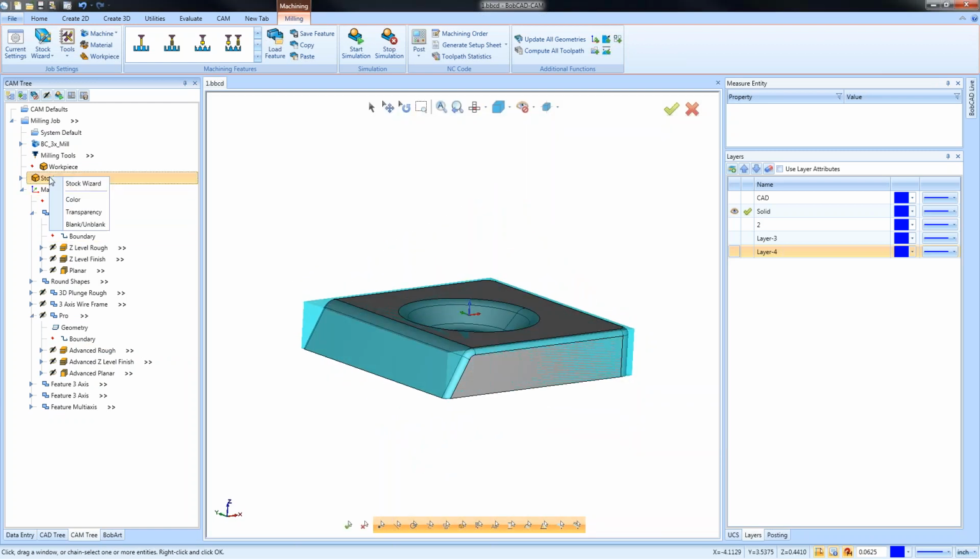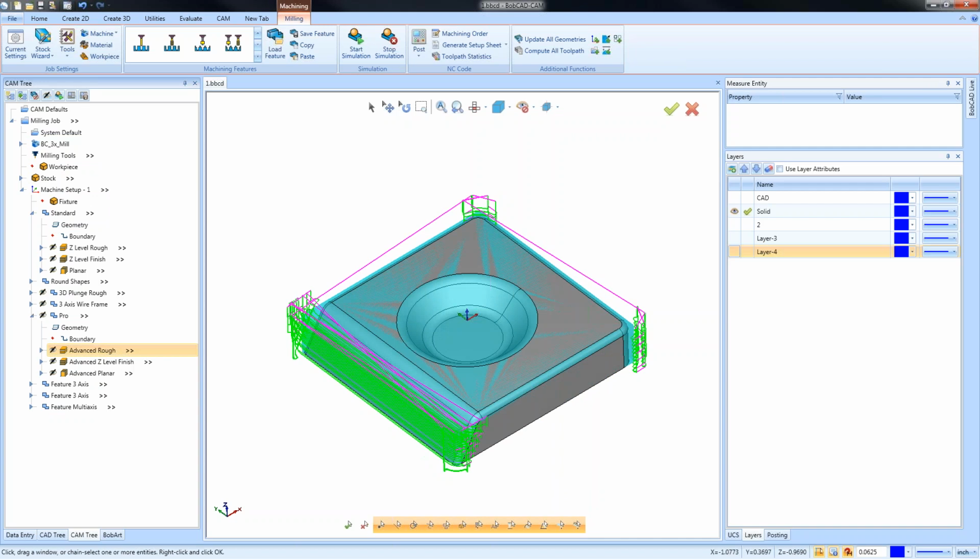So let's go ahead and I'm not going to get into controlling. That's going to be day 2, but again, the main difference that I'm focusing on right now is the way the toolpath is generated based off the stock. Zlevel Rough, the center of the tool will go to the stock. The advanced rough, you can tell it to start outside of the stock, and you can also control whether it plunges or doesn't plunge.